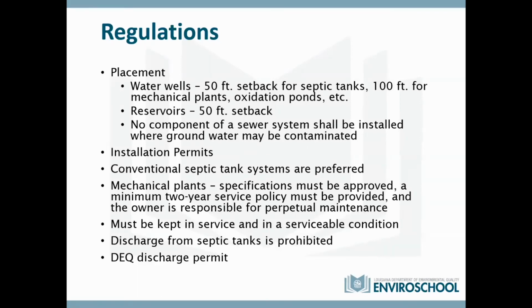Again, I said this earlier, but conventional septic tank systems are preferred if you can pass a percolation test. And then for mechanical plants, their specifications have to be approved. There's an engineering group at the Louisiana Department of Health that approves all these mechanical systems. A minimum 2-year service policy must be provided. And then after that, the owner is responsible for perpetual maintenance. They have to be kept in service and in a serviceable condition. And discharge from septic tanks is prohibited. Remember I said that earlier. These fill lines should not discharge. It's actually prohibited in the sanitary code.